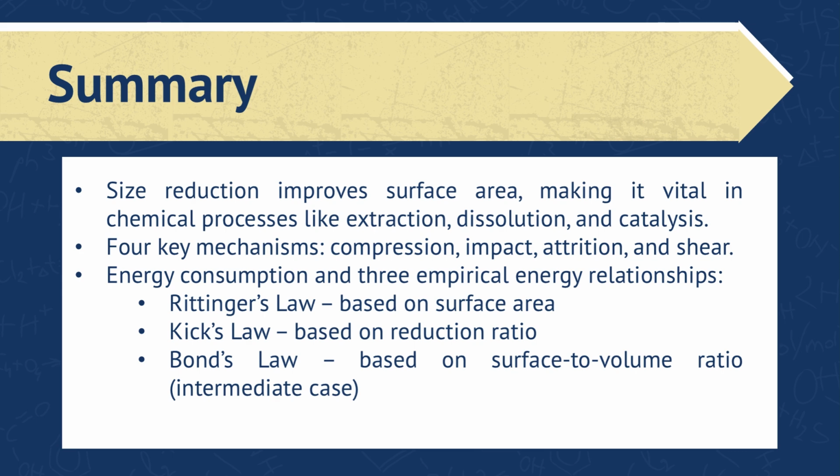First is Rittinger's law, which is based on surface area. Second is Kick's law, which is based on reduction ratio. And lastly, Bond's law, which is based on the surface to volume ratio and is an intermediate case between the other two laws.